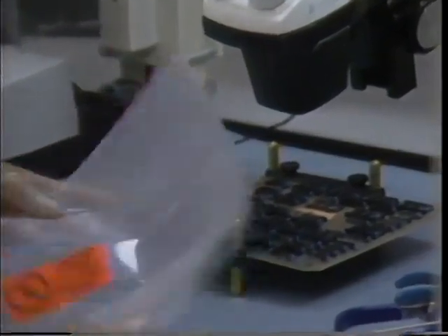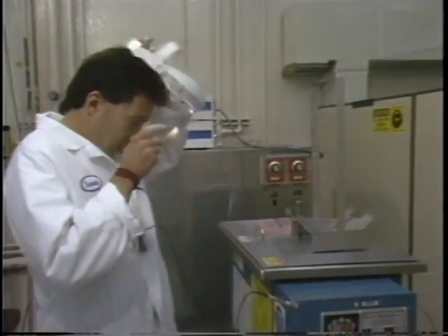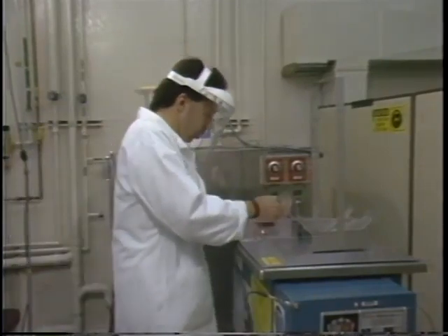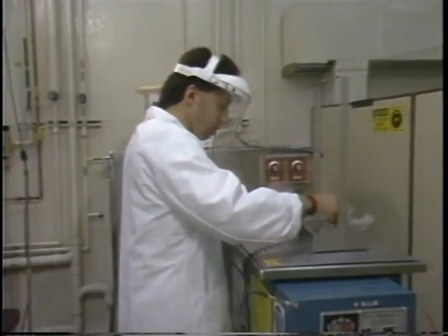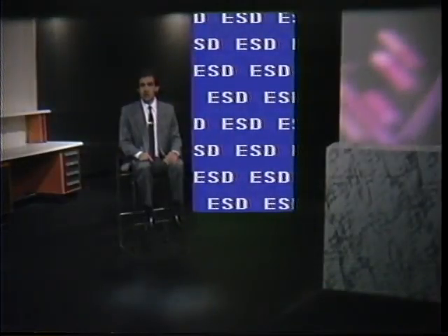Pay attention to ESD certification labels to be sure they are valid. Look for the ESD caution label on all hardware and handle these items with care. Be aware of what you are doing to ensure that the end product will be free from defects. Without ESD controls, we all lose. ESD prevention pays off in higher quality products and in satisfied customers. Your help is critical. If we all work together, we can eliminate ESD damage and improve the quality of LMSC products.